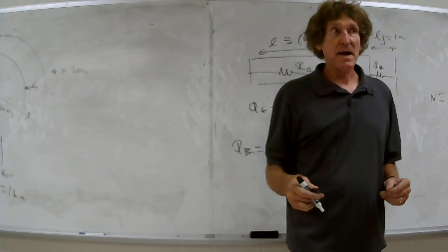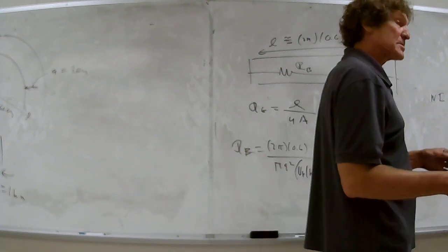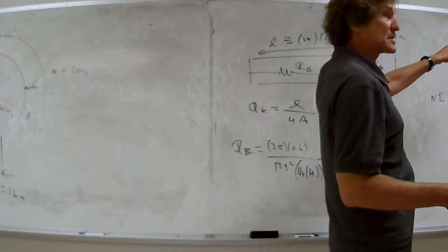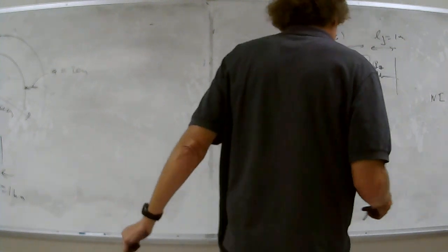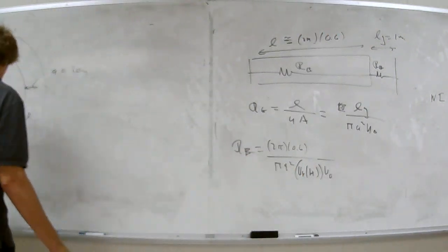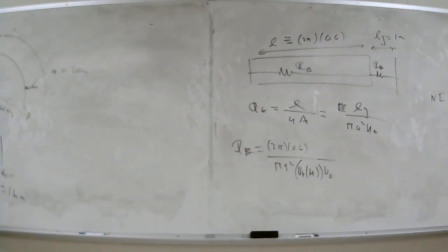Yes. Now, here's the deal. That's the flux flowing, right? That flux is flowing all through here. It's the same in the gap as it is here, right? What we need to do is find out what the H field is, or B field here. If we know that's the flux flowing, what is the H field in the gap?